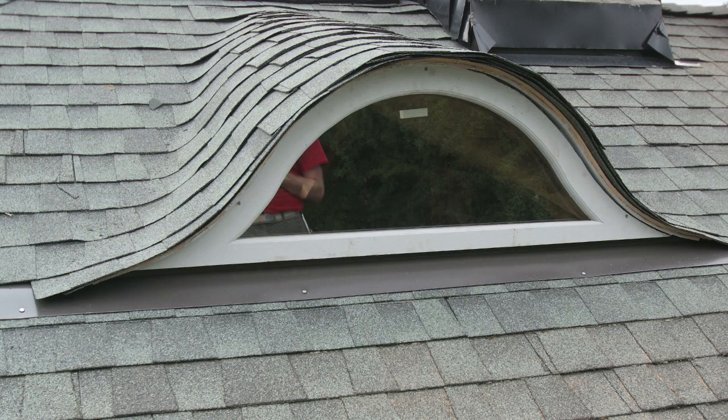In order to build any project that involves complex geometry, it helps to start with a good drawing. For an eyebrow dormer, a sequential set of full-scale 2D drawings are actually used to develop the 3D shape, finding the unknown from the known in each progressive step. The drawing process begins by laying out the desired width and height of the dormer opening's front elevation.